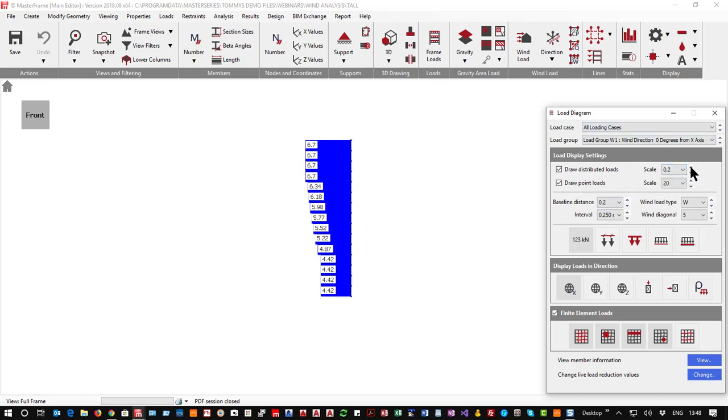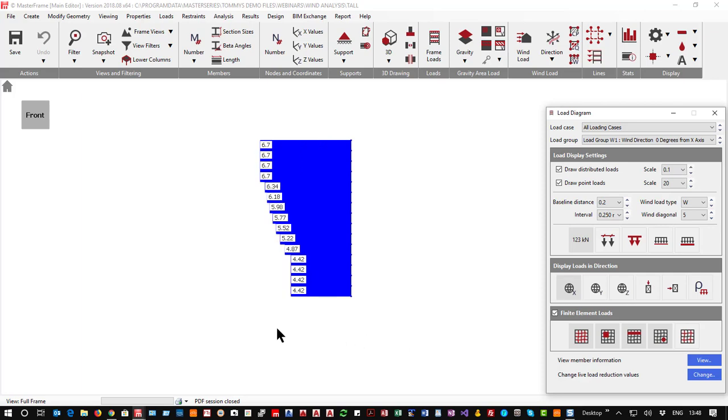So you can now see, and I'm going to scale these up, that you have a uniform portion, a tapered portion, and a uniform. So in essence, for tall structures, whatever your frontal B width is, that's constant up to a height of B, and from the top down for a height of B. And then the middle area is tapered per floor level.